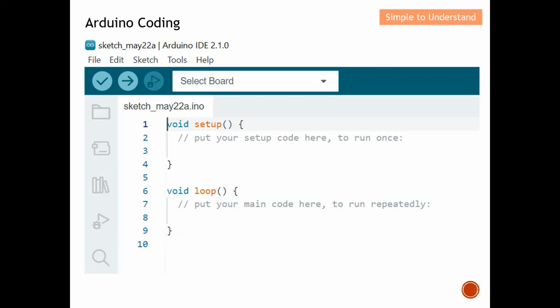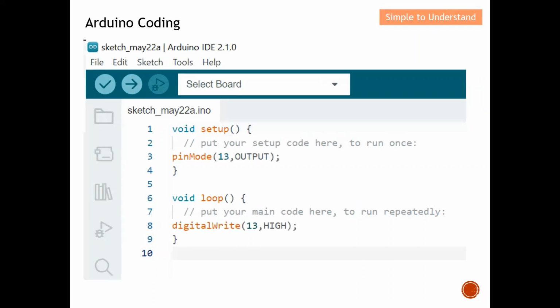Let's take a look at our task number 1. How can we turn on the LED? This is the source code that I have written to turn on the LED on the Arduino Uno board. Under this instruction here, we want to define whether pin 13 will be input or output, or pin 9, whether it will be input or output or whatever. Over here, we only need to do it one time. For example, in this particular video, we only use pin number 13, which is illustrated here.